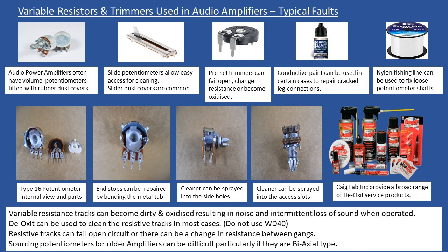Now, the same company will make switch cleaner, and that is a different product to the blue can WD-40, right? So in that case, if that's a high quality switch cleaner, great, you can use that, but don't spray the WD-40, right?